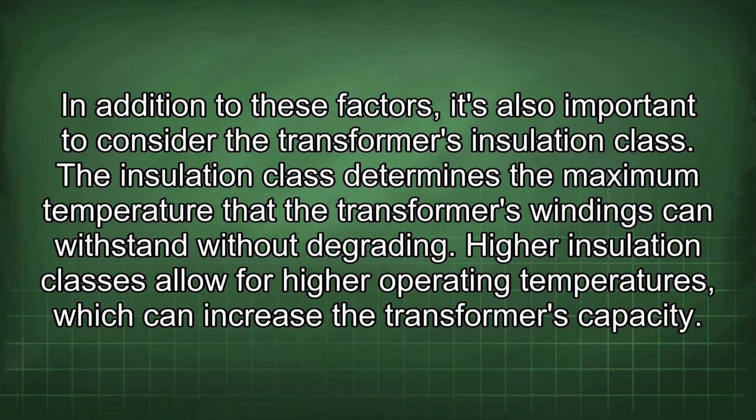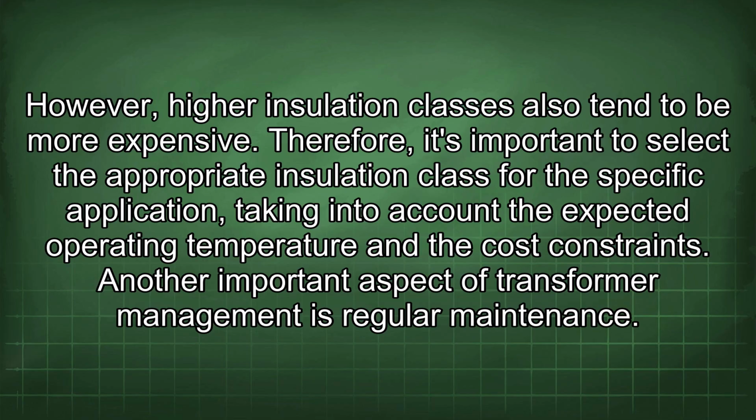In addition to these factors, it's also important to consider the transformer's insulation class. Insulation class determines the maximum temperature that the transformer's windings can withstand without degrading. Higher insulation classes allow for higher operating temperatures, which can increase the transformer's capacity. However, higher insulation classes also tend to be more expensive. Therefore, it's important to select the appropriate insulation class for the specific application, taking into account the expected operating temperature